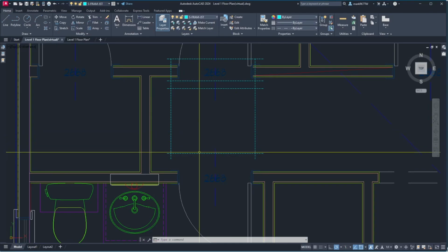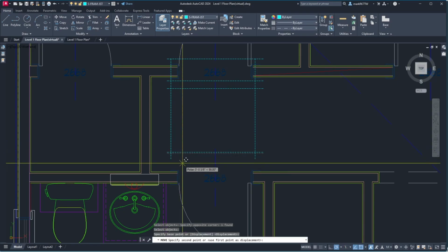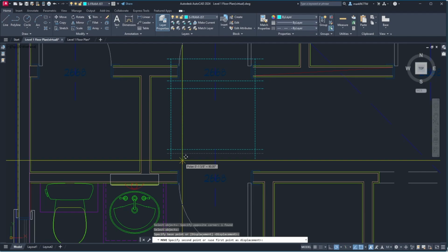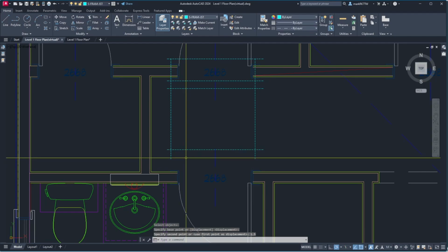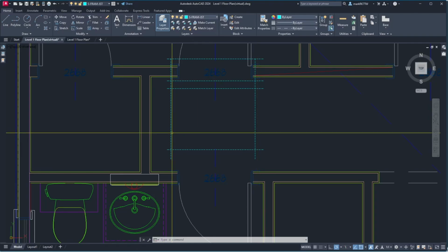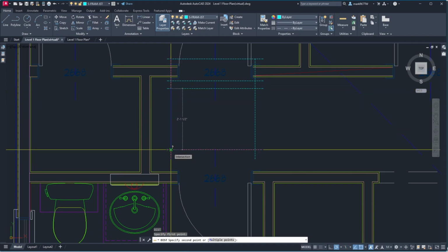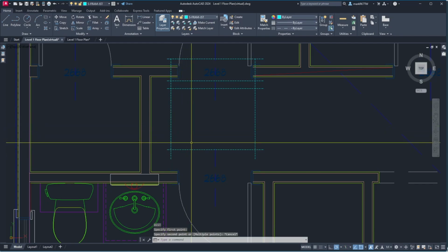So this was truly OTO, so it was outside to outside. That means I need to move that up 1.5, the thickness of itself. Now, the distance from here to here, out to out, is 34. So it's 35 and a half. Oh, minus 34. Minus 1.5. So this should be 23. Okay, it was 27. So, 25 and a half. That's right. Okay, so that's good.